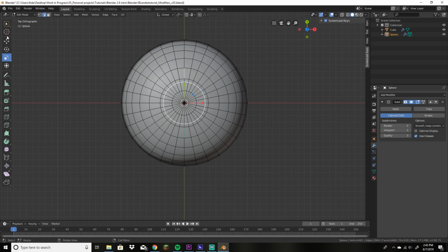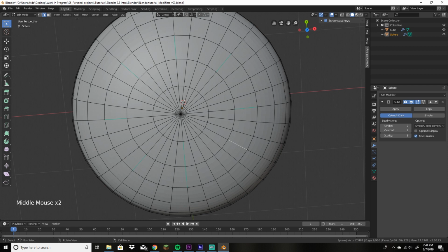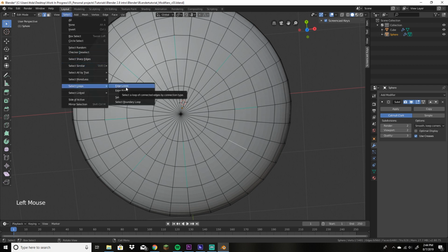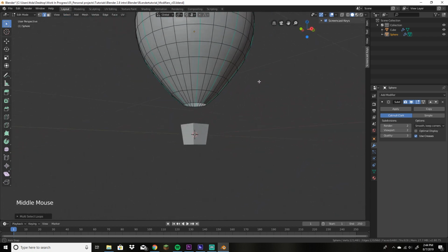I'm going to switch off scaling too. That way it's not in the way. So selected those two, selected these two, and then also the 45s. So I guess northeast, southeast, whatever. I've done enough reciting of directions. So once you have those selected, we want to select the edges the whole way down, but I don't want to do it by hand. So if I just go to select loops and then edge loops, that'll select the entire edge.